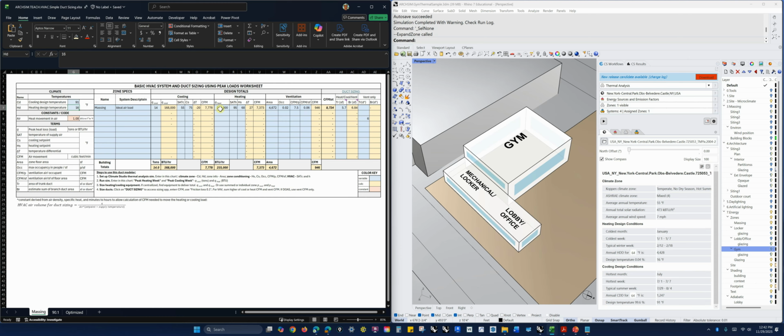So that's why we have a higher heating load than cooling load. But since we're delivering air with a lower temperature differential between the cooling supply air and its set point, we actually have more CFM that we need to deliver this smaller amount of load for cooling than we do for heating.